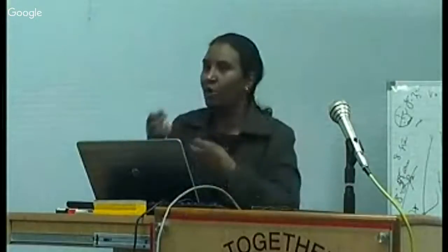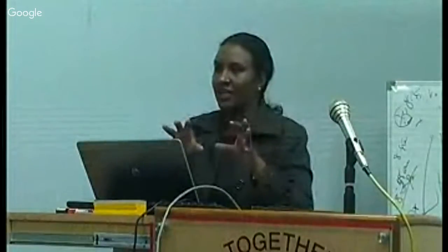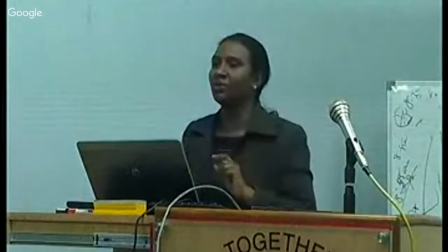So what will you do? This modulation index you will remove, and you will put an input block where you take the data from the real time. What is modulation index? It is from your fundamental voltage and DC voltage. So if you acquire the fundamental voltage and DC voltage, give them to some block which will calculate the modulation index. That modulation index you give to your problem, and here you will remove this.